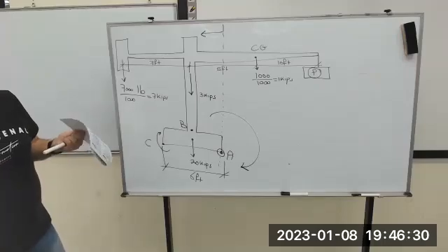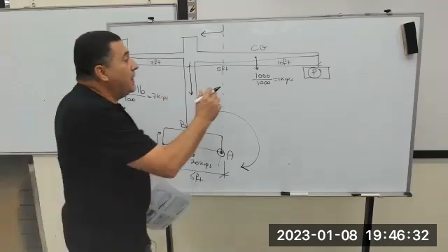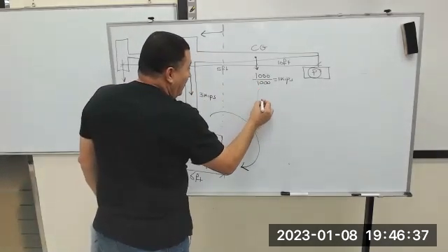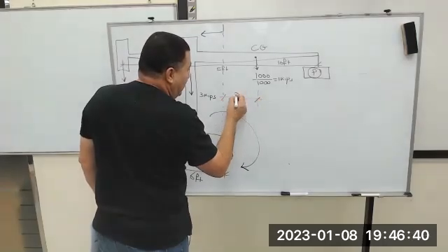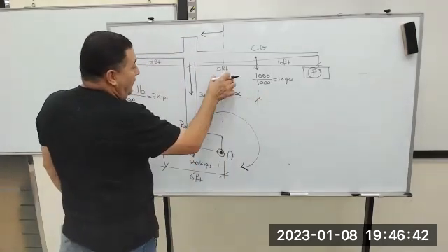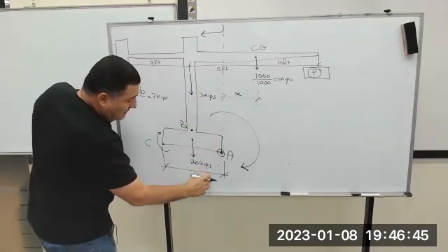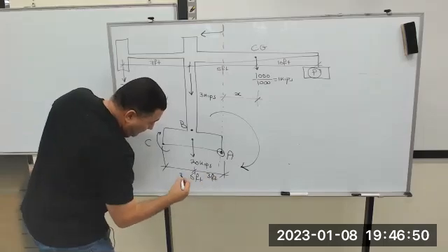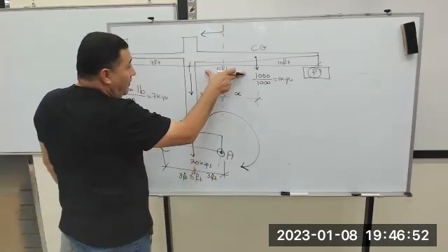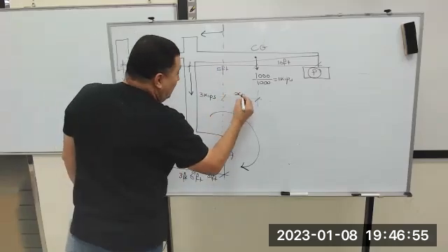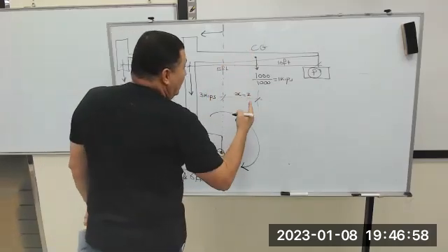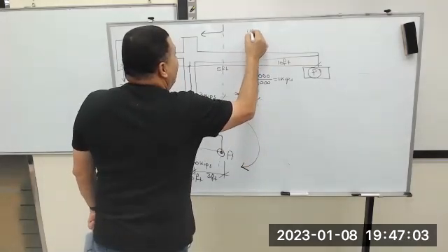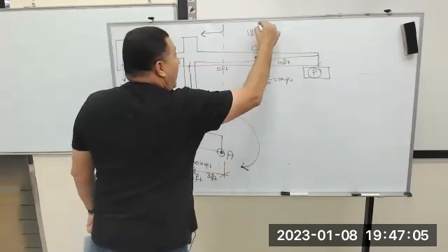But what is the equation then? The force produces a moment here, right? This moment is distance multiplied by force. This x is equal to what now? 5 minus 3, because it's 3 feet. Correct? So 5 minus 3 feet. Now this is equal to moment: force multiplied by distance. So give the first force, which is 1, multiplied by 2, the moment of it. Correct?